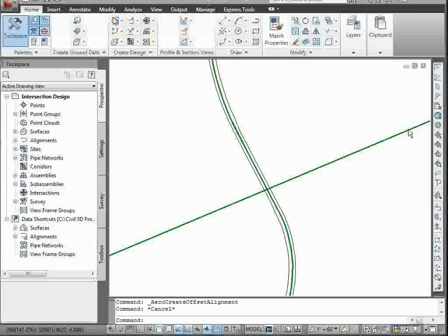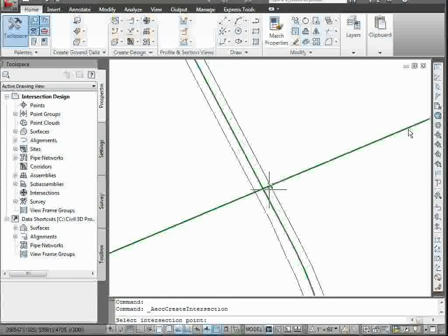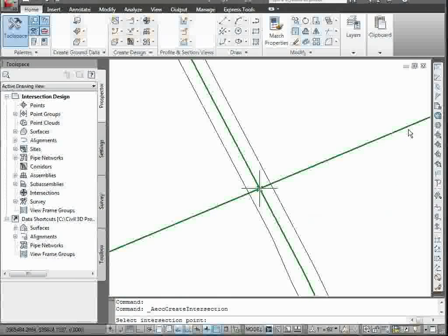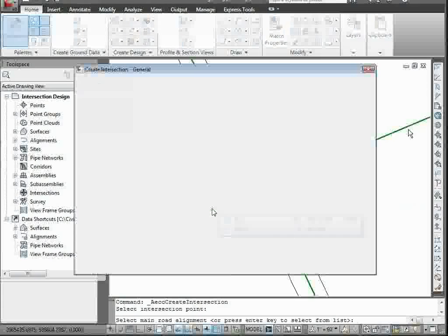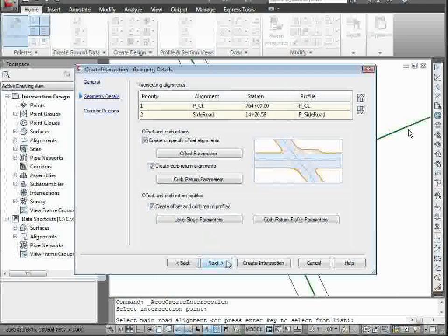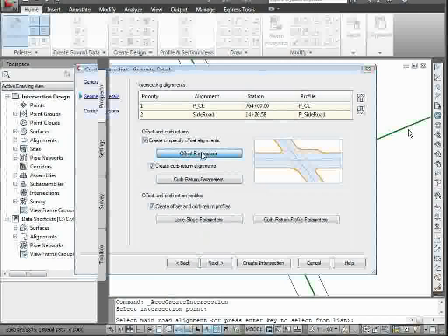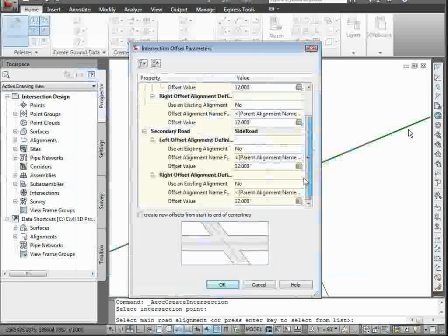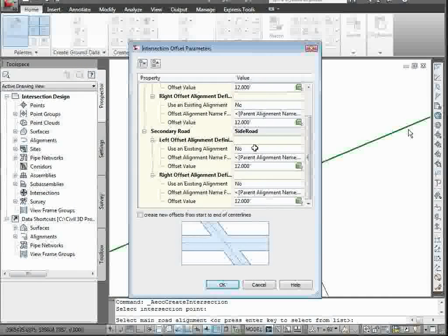So you need things like bay tapers, oscillating widening in a curve where you go from one radius to another, or straight line interceptions. All of that we have available via our widening options. So you create your widenings, and then we have automated intersections that will let you take that data. And what you're seeing here is quickly an automated intersection that will come in and ask, what are the side alignments that are going to control this? Those, for example, could be our widenings. And in a main corridor, there may not be any side alignments. It may be just following the typical section.